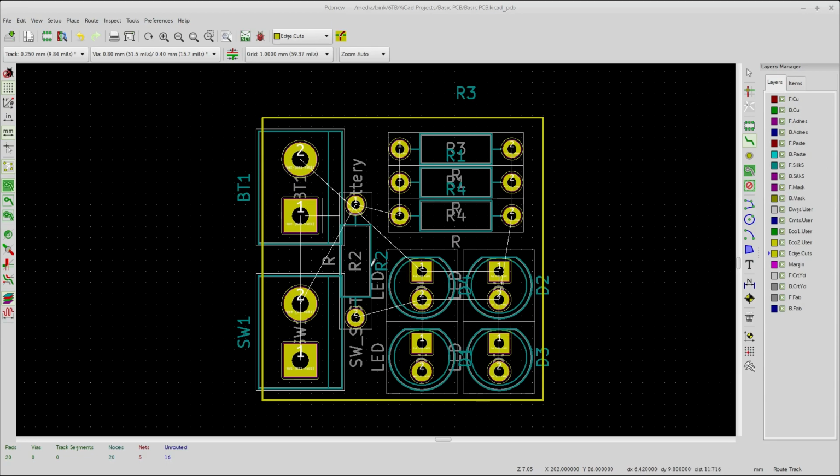you're going to end up with double traces going along here on the top and the bottom is what I'm trying to say. And then you'll block yourself out again. So probably try to think ahead of the game as much as possible. And I'm thinking that I'll start with kind of some outside traces here. Be very careful about running things from one side straight across, because that's a wall. So think walls. You don't want to create too many large walls right off the bat.